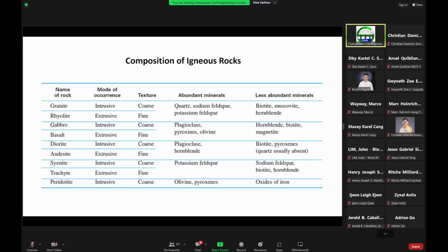When I was in the industry for 3 years, these were the places where I normally went, almost every month, because I was visiting these geothermal sites, assessing some slopes. These are normally the rocks that I encountered, especially these andesitic rocks, which are prone to weathering processes, and they cause landslides. When they become fully weathered, they can cause landslides in these geothermal sites. It's a bit tricky.